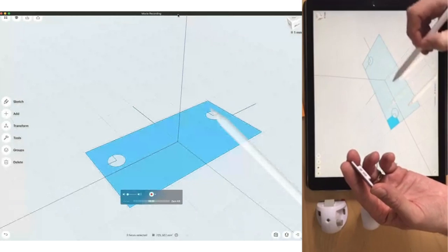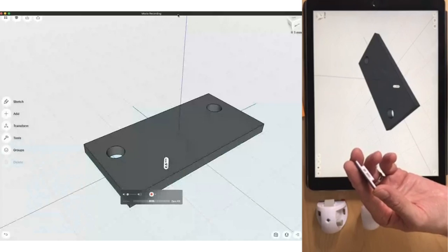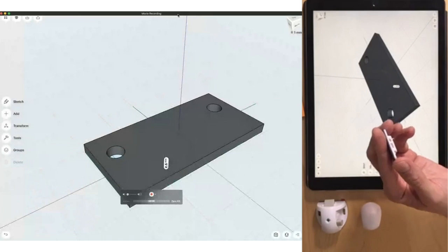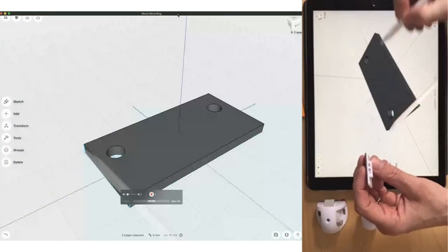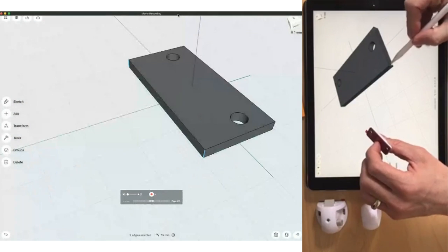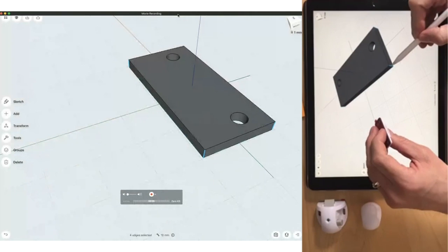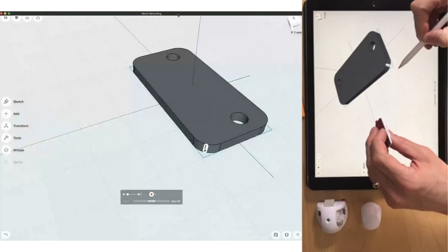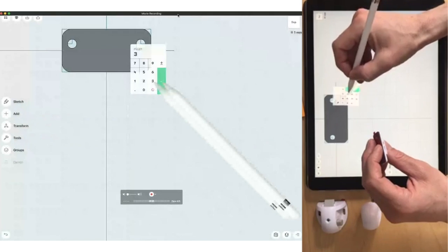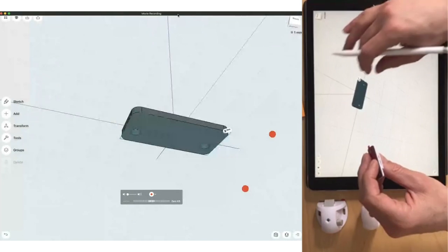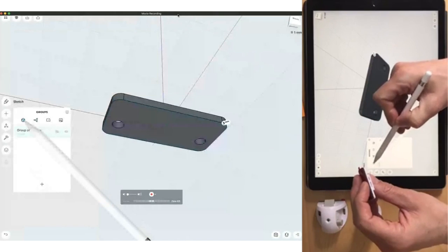So I will select this, and go 2.5 millimeters up. And I mentioned before, try to break stuff down into logical steps. When do you do what? Because I have to build also that compressible material below, I will now first round these edges by selecting these edges and then swiping to the correct area. Let's say these should be 3. And then I can use the extrude command.